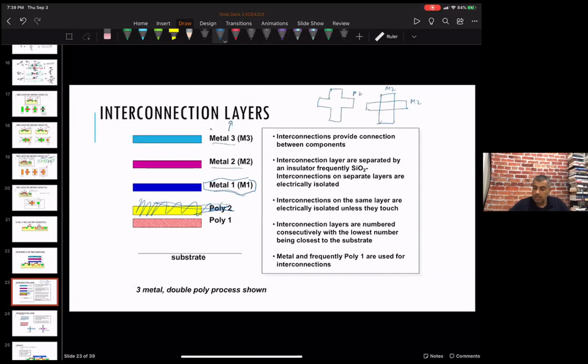That's what it'll end up being. But if you do metal 2, and then you draw another rectangle in metal 3, although they're overlapping, those two don't short together because metal 3 is on a different layer than metal 2. It's going above it. And unless I draw a contact between them, they don't short together.